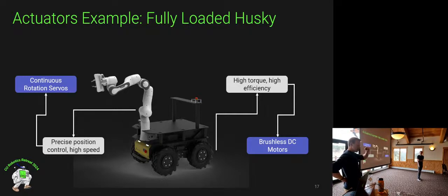Small ones, like six volt DC motors, are maybe under $10. Pololu sells geared motors that I think are like $5, $6, things like that. But it really comes down to how much torque you need, how big you need the motor to be. Obviously, the cost scales with the size of it, or maybe if it's some specialized sort of thing. And brushless motors are generally more expensive. They're more complicated, right? There's more engineering that goes into those systems than a brushed motor.